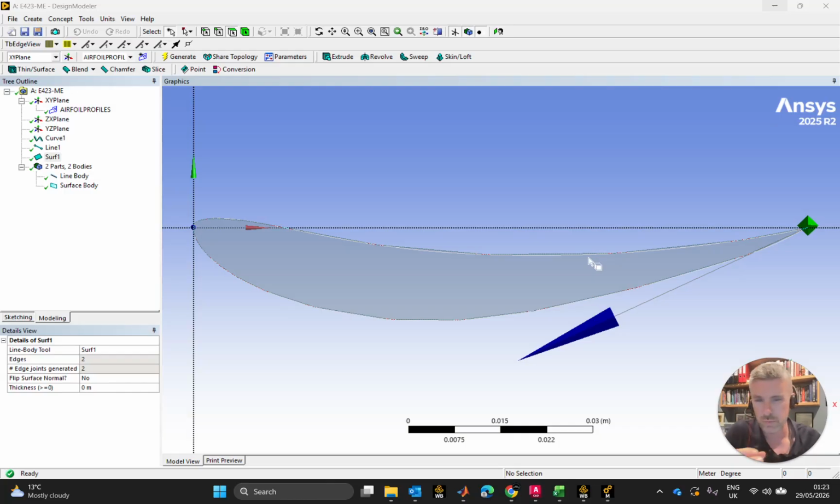Now the mesh will kind of resettle itself on every iteration on a design point with changes to the geometry, but if the changes are very small, what tends to happen is that we could be moving into singularities within the flow domain, within our discretized space, where we're getting artificial numerical inflation, especially in areas around the trailing edge.